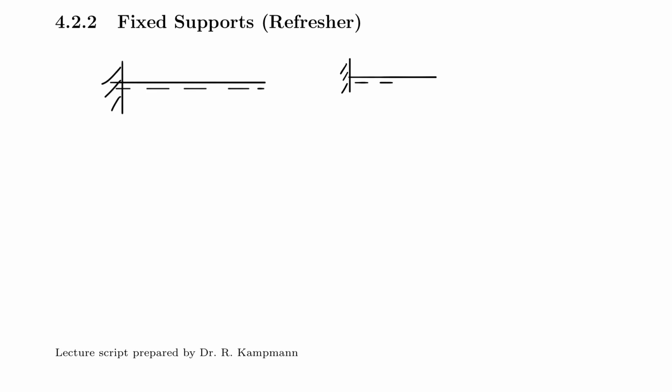And it doesn't really matter how you do it, as long as you understand what the purpose of this symbol is. And the most important thing that we remember is that we needed 3 conditions to be true for our systems so that they can support forces. And what were those conditions? We said that the sum of the forces in the x direction must be equal to 0. The sum of the forces in the y direction must be equal to 0. But also the sum of the moments about any point must be equal to 0.